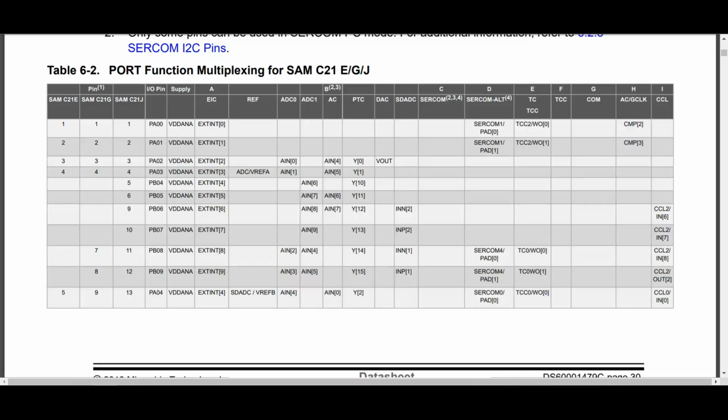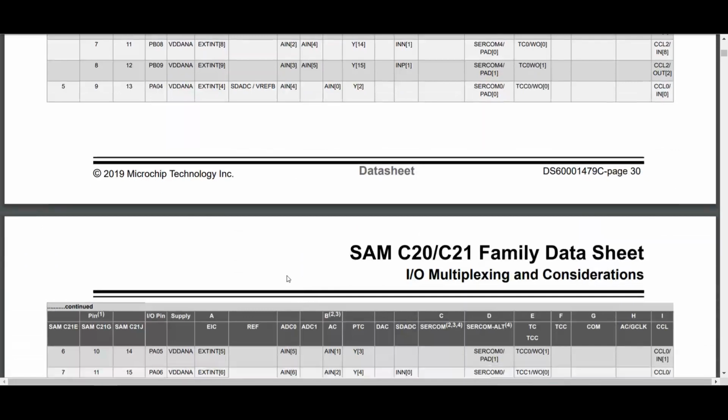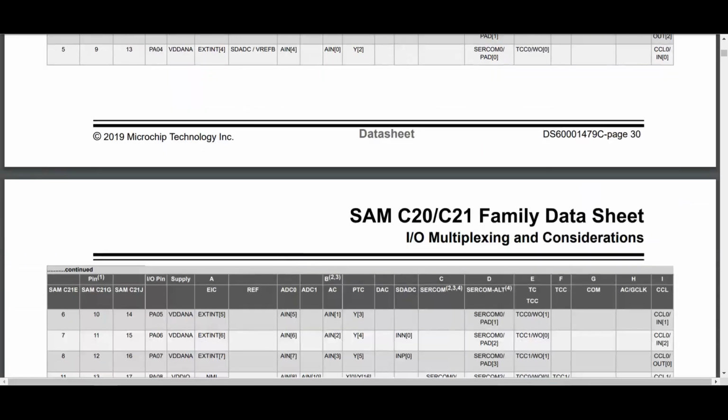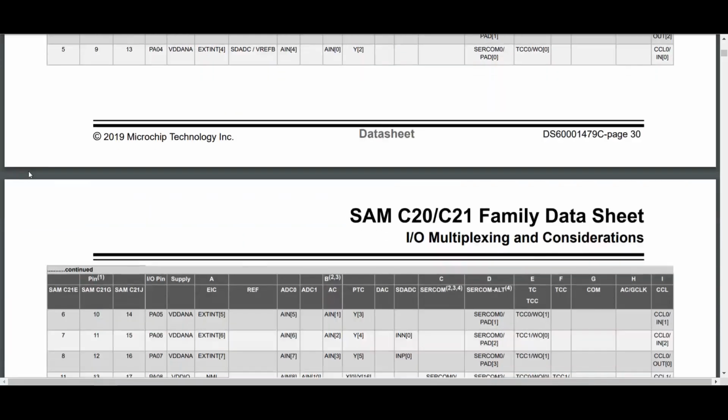That means analog inputs 2 and 3 of ADC 0 are not accessible by any pin on the chip. To actually get to a working pin, we have to jump to pin 5, which is physically in software as analog input symbolic number 4. And then symbolic input number 5, PA05, is mapped to pin 6, which is exactly what I did on the circuit board. It may seem weird that I skipped 2 and 3, but that's because they don't physically exist on our chip. Now, let's take a deeper look at the problem.